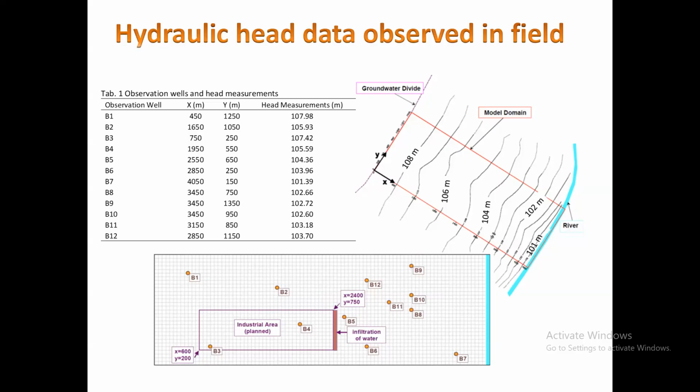You create a conceptual model, then you set up your numerical model, you simulate the state variable of interest, whether this is head, a contaminant concentration, or stress in a beam, whatever it is, and then you compare it to what you are observing in your experiment or in the field, and then you keep updating your model until your model is simulating what you are observing. So this is a general concept in any application.